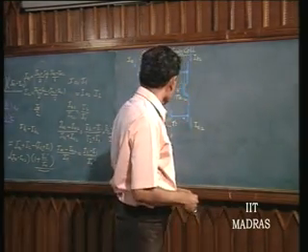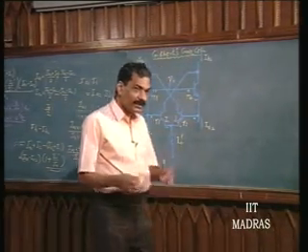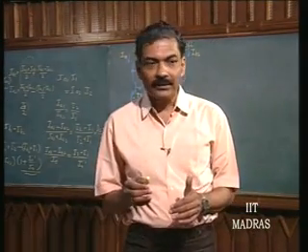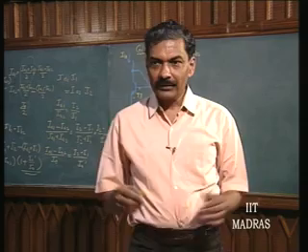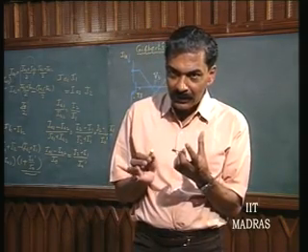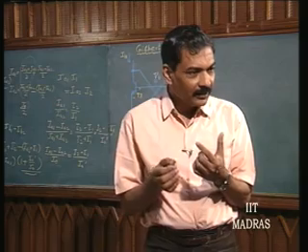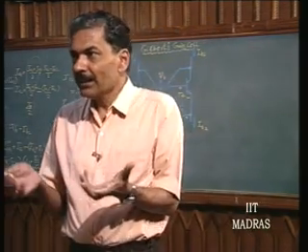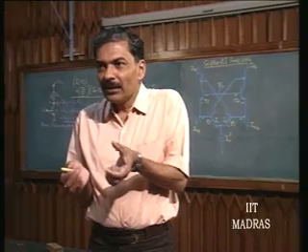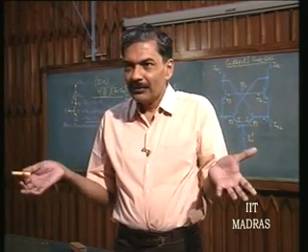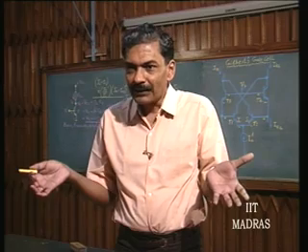So, this is what is done here, and it is truly wideband primarily because you are at all times dealing with only currents, and the voltages involved are only diode voltages, and therefore, the capacitors to be charged will be those capacitors across the diodes, and therefore, they are to be charged by a very small magnitude of voltage, and therefore, it is going to be very fast.